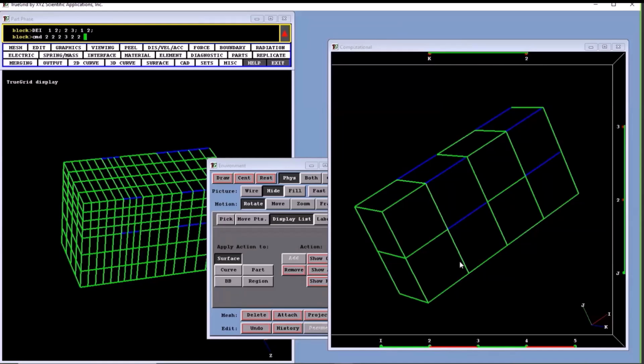So the point is that this is known as an I edge because we have intervals in the I direction. If I'm selecting multiple edges, they have to be all of the same type. I cannot have an I edge and a J edge in the same instance. How do we use this? Because we've talked about commands that have regions, and it's the minimum and maximum of the 3 directions. Well, how do we do 2 intervals or 2 selections along nodes?